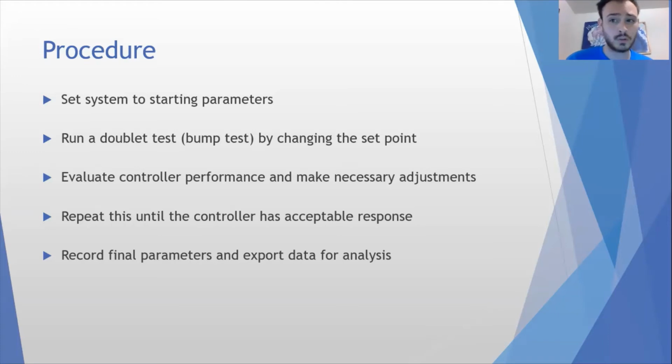Once you have determined which of the 3 you will use, you will adjust parameters such as Kc, Ti, and Td to determine the proper reaction rate of this system.